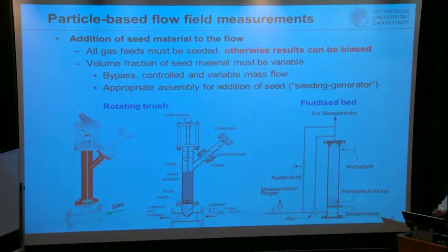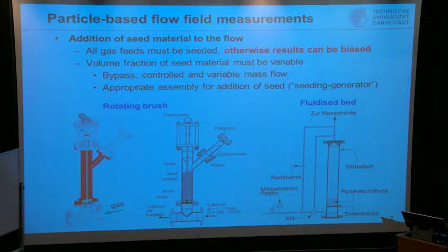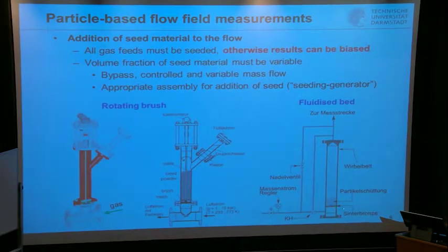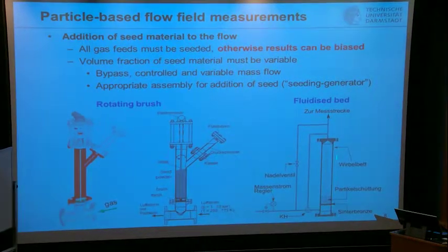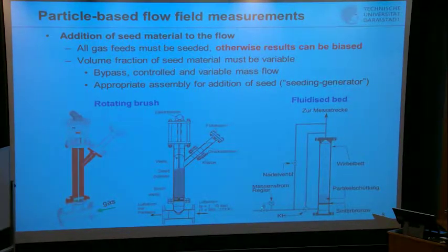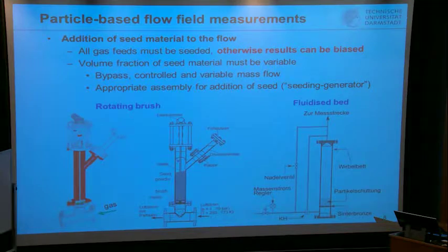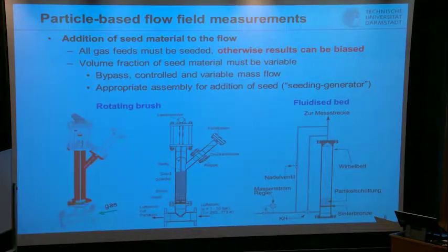To my understanding, or to my experience, the best is actually something like a fluidized bed, where you have your tank with your containment, where you have your particles in, and then you send, let's say, your gaseous flow. You create a fluidized bed. You have here a contraction with a small aperture, a small nozzle that accelerates the flow, and thereby, even if you have, by humidity, particles that stick together, by the forces during this acceleration, they partly break out and disconnect again. And very important is that you do have here a bypass.